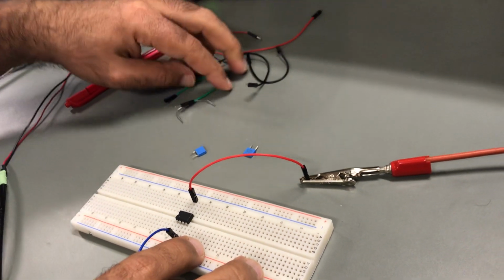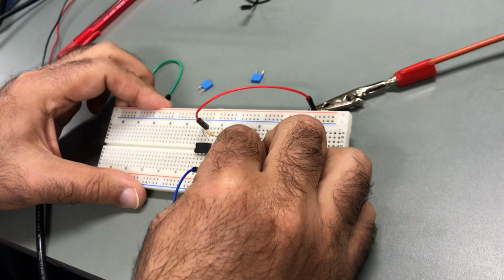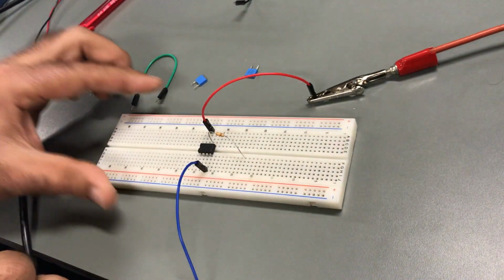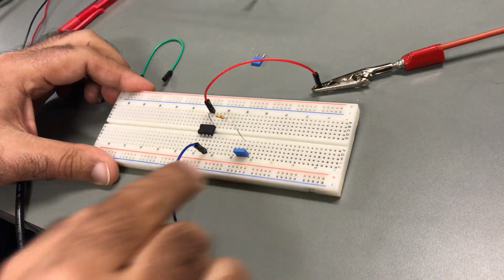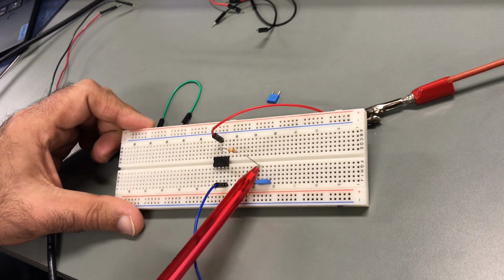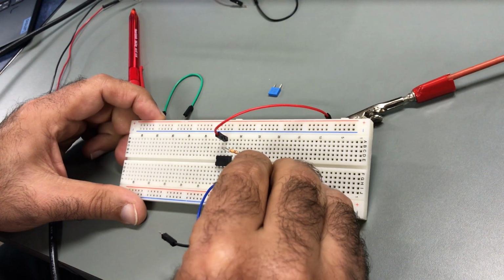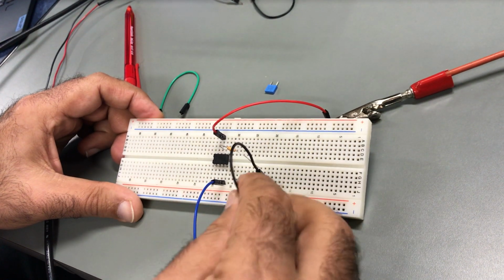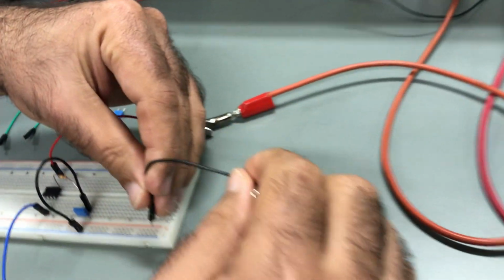Then I can connect the resistor to pin number 6. So pin number 6, which is this guy, I will connect this resistor, and in series with that I will connect the capacitor here. So the resistor is connected to pin number 6, and the capacitor is connected in series, and this leg will be connected to the ground, like what we are seeing. And then I will take this guy as my ground, and I will connect it to my circuit like what you are seeing.